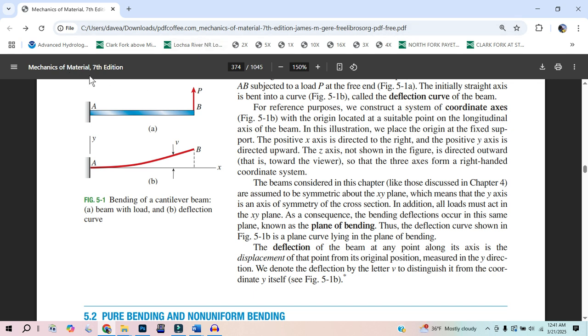Think of you at point A. What do I need to do? I need to pull down on that. Okay, now I'm just spinning it in place. So I also need to pull down, but then I also need to apply a moment, and that's going to cause it to spin this way. So I need to apply a moment this way, which is an upward force and a downward force, separated by a little bit of a distance. That combination will get that bar to be totally stationary in outer space.